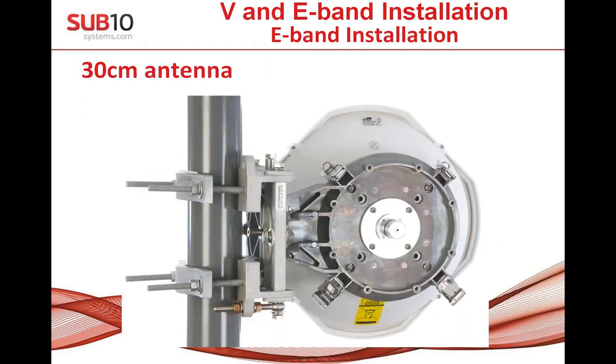If you install just the antenna, it's looking like this one. You have a 30 centimeters antenna. On this is the waveguide to the radiator, or this is the end of the radiator. It's normally protected by a cap. Take this plastic cap, and my suggestion is do not throw these caps in some garbage. Hold it, because later on if you need to do some manipulation, it's always good to have this plastic cap to make protection. The reason is this is a waveguide. This small hole in the middle is the waveguide, and if some dirt goes in, or even water, it will definitely affect the quality of the signal.